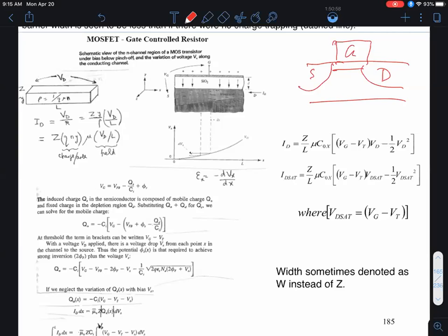But if they use MOS, once again, they would make the oxides much thicker so that they'll be radiation hardened. But typical computer chips, terrestrial applications, generally speaking, they'll guarantee a reliability of about 10 years or so, okay? And companies count on the fact that consumers typically don't even keep their electronics for 10 years. They get rid of them after a few years. Unless you're like me, I still have my old VCRs and videotapes, and my children make fun of me.